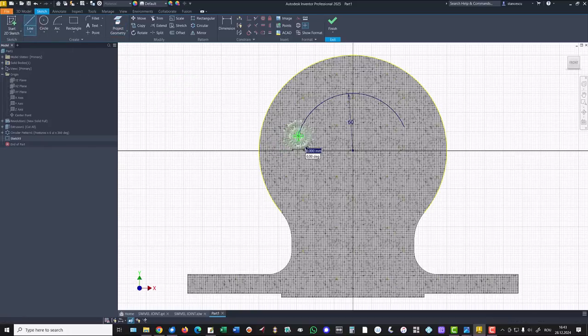Now I project this arc and I use line to draw an arc. I keep pressing the left button and I go to that projected arc. The same to the right. Here. These 2 points are on the same horizontal. This point and this point. These 2 arcs are identical with the same radius. Then we apply the dimension radius 80.